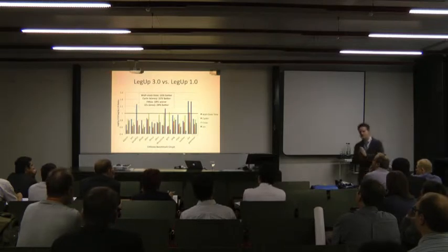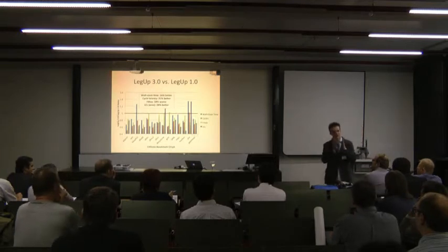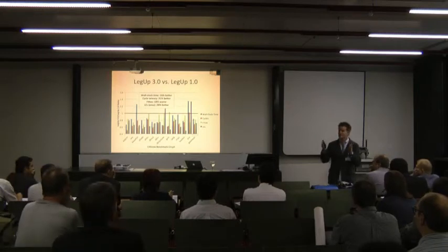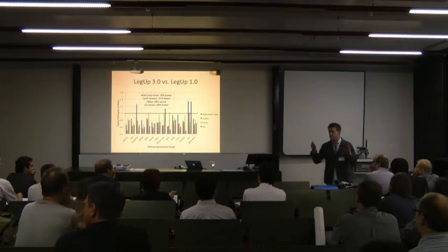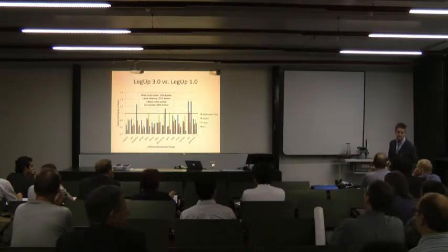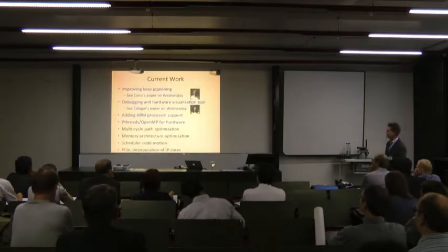So sometimes it turns out in high-level synthesis, if you use a longer clock period, you can chain together multiple operations within one clock period, and that can reduce your number of cycles. As long as your number of cycles is reduced by more than your clock period got worse, you can end up with a winning wall clock time. So we effectively tuned for wall clock time. Area a whole lot better, about 28% better.